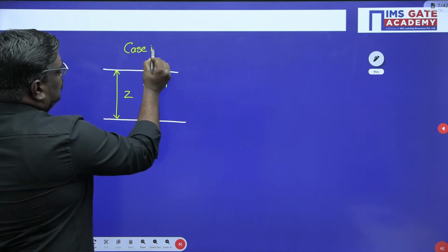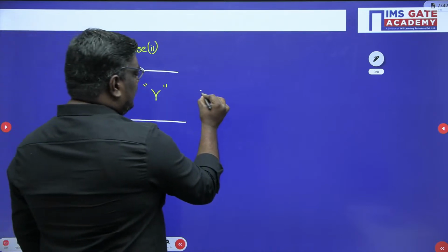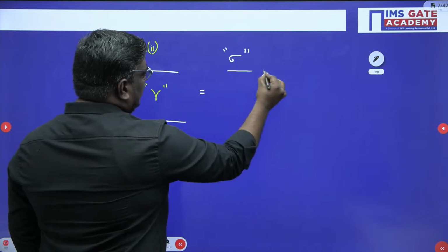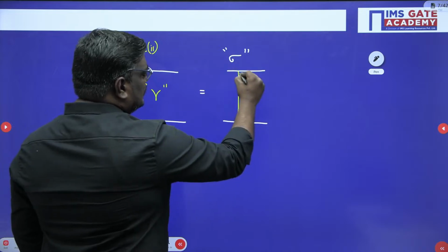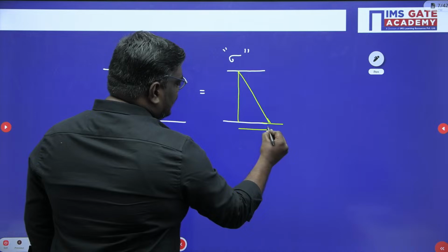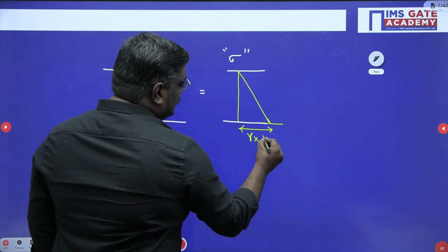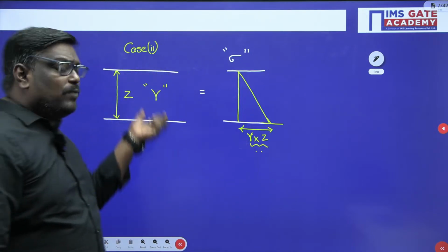Now my dear students, if you see how the total stress distribution will be, if I represent total stress as sigma, here it will be distributed in a hydrostatic way, or you can say linear way, okay? The value here will be equal to gamma into Z. Now do you find any water table here?